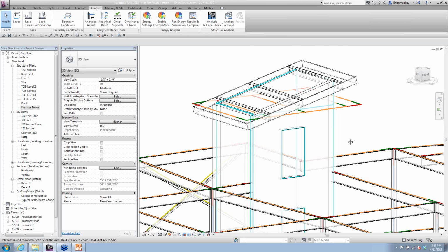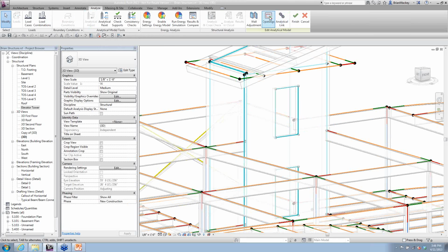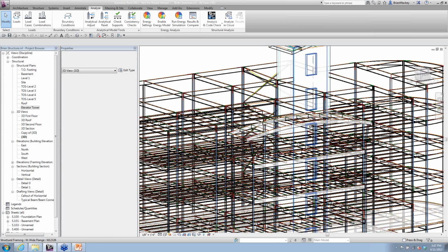The other thing when we're talking about walls, the openings command will work the same on walls. So for some reason you might not want to calculate an opening. Again, you might have a depression in the concrete. You might have like a brick ledge in the concrete, and it might stop at the brick ledge. You want to get rid of an opening going through. Whatever reason, it might be a small enough opening and you don't care about it. Same scenario, adjust analytical. Come in here to openings, and you'll see now I have checkboxes for the openings. I just double-clicked it. I have checkboxes for the openings in walls as well. So that openings command is not just in floors, it's also in walls, so you have that same scenario to be able to go through and adjust those.